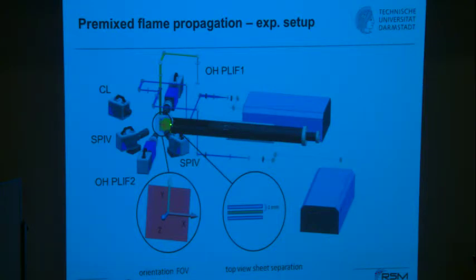Then there was an ignition, and a flame kernel developed. Why so long? We wanted to have fully developed pipe flow turbulence by that time, and we wanted a large diameter such that we had a certain distance in space where there is not yet any air entrainment from the surrounding co-flow, which was operated at similar flow velocities.